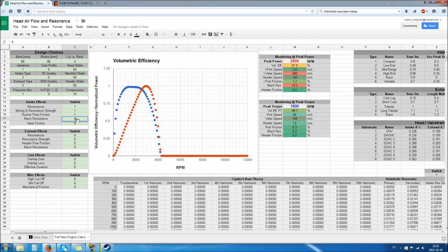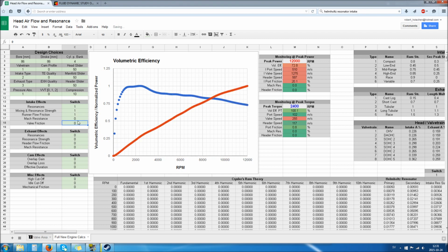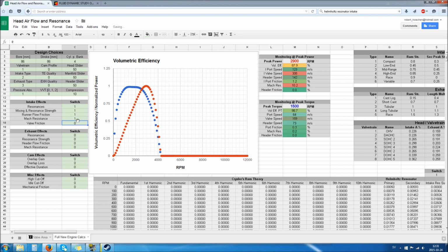Alright. If we switch it off again, you see, yep, that engine still breathes. That's just a normal resistance. But supersonic flows have a lot more resistance to them than non-supersonic flows. If you're approaching the supersonic barrier, the sound barrier that's also pressure dependent and temperature dependent and stuff, then you will run into a lot of resistance for your engine breathing. This is not modeled entirely correctly, but the effect really is very strong and it completely strangles your engine.